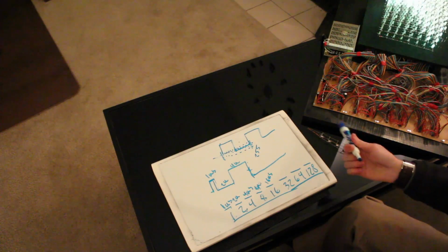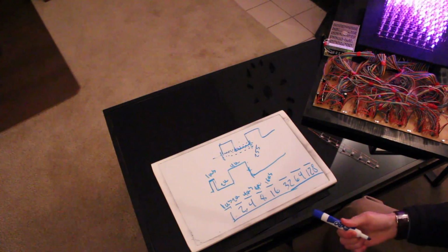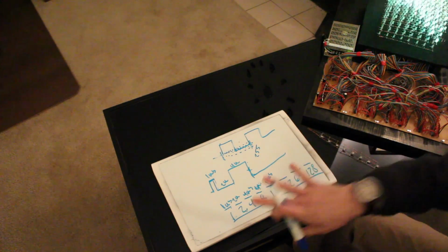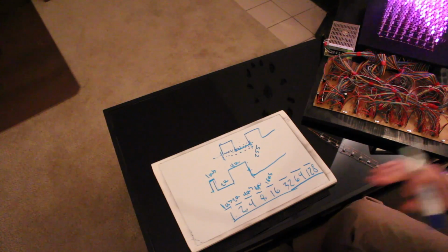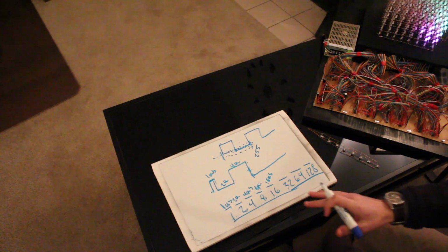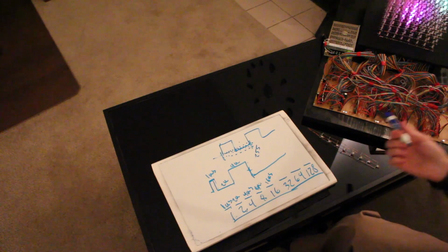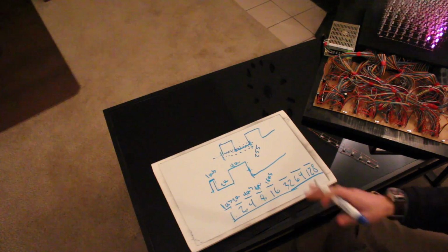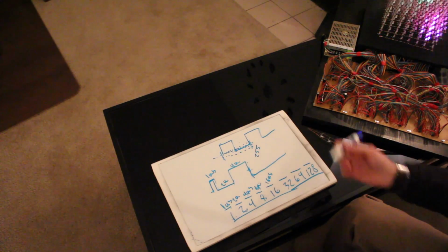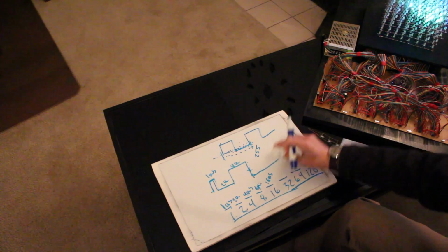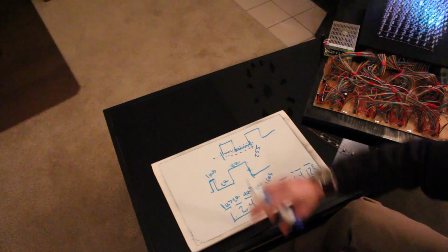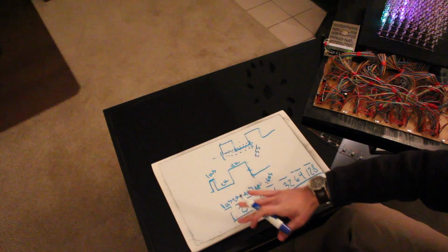In my case, I had to do software modulation. There's no way I could use the Arduino pins, which are nice and easy to use. That's hardware output, very effective, low CPU overhead. But since I have to do my modulation in a homemade way, this is what I chose. So I have a free running timer that's just continuously counting, and I just check it.